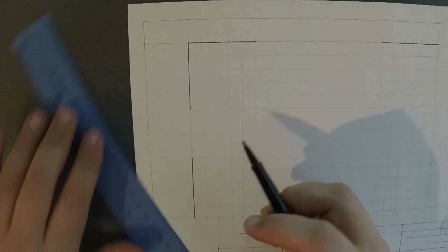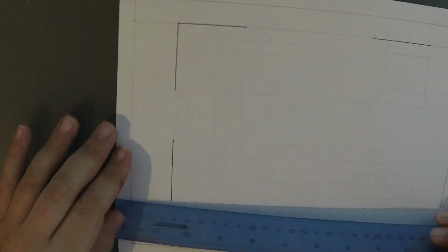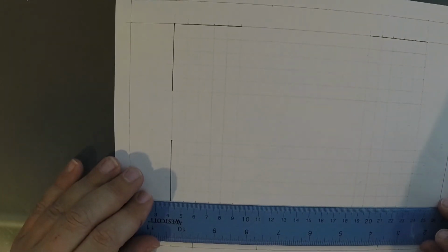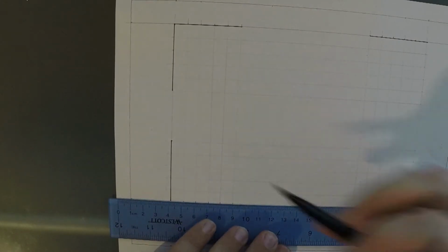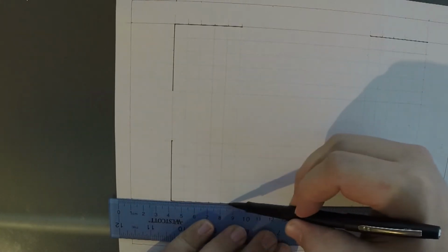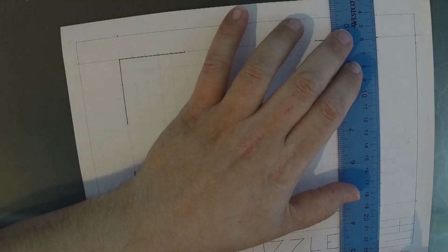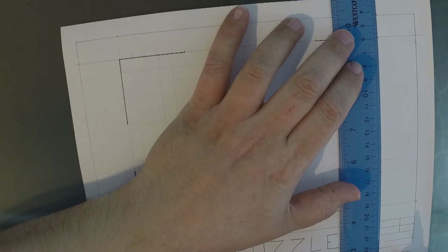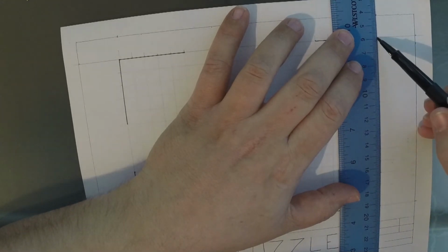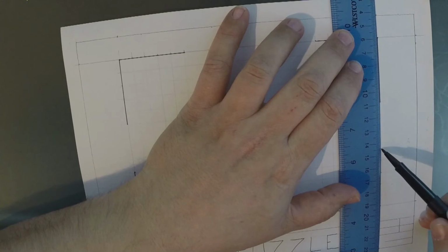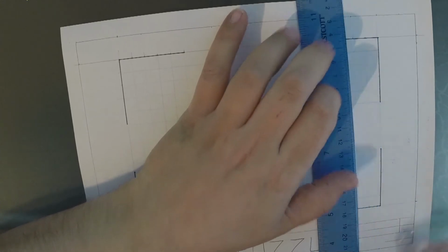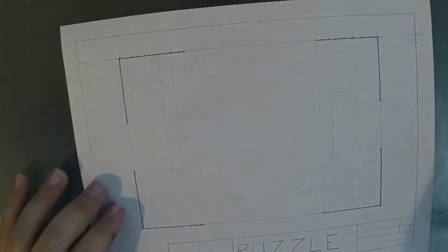Trying to do a good job now because you don't want to erase object lines. And honestly, because I'm using a marker, I can't erase my object lines. So I know I'm keeping all these things, and by drawing the top and bottom or left and right all at once, I'm actually saving time. I don't have to reset the ruler twice, and the lines are parallel with each other.